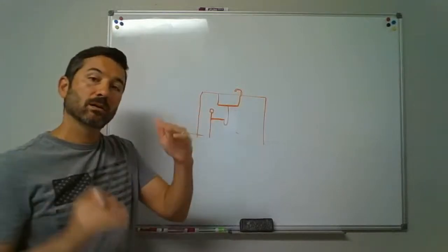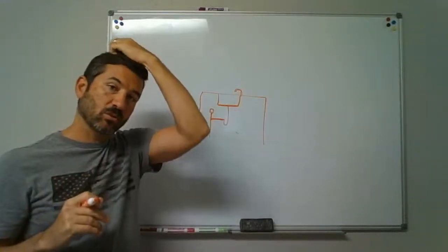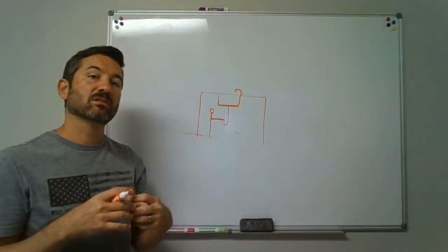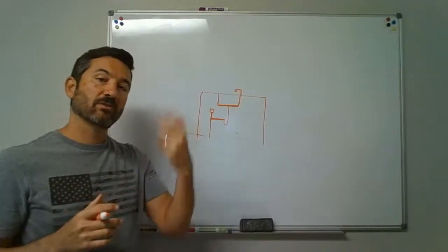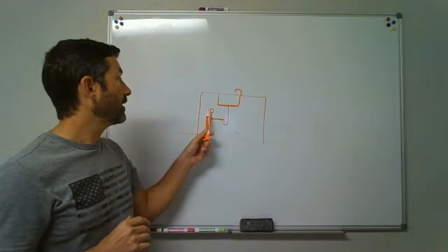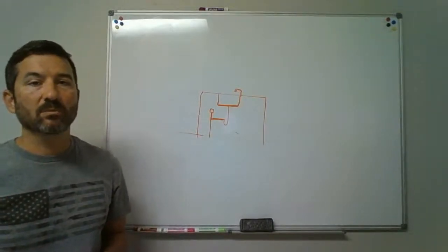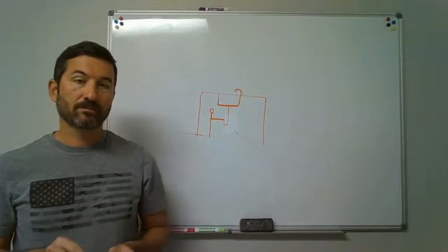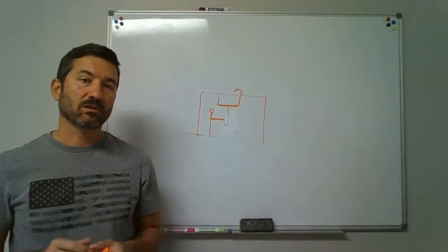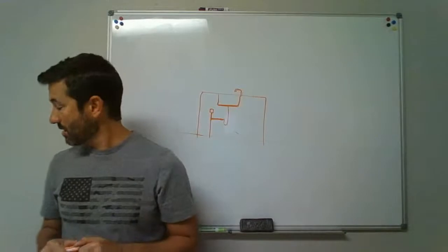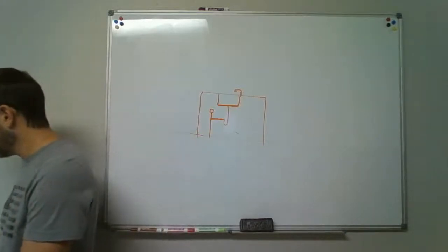It's a one-way check valve that's going to allow air to be drawn into the system, and it will seal off and keep the gas from coming out. And that's what you're really going to see most of now, because that's going to save you a lot of time and money on the extra routing that the other one's going to cause, and you can just slap an air admittance valve up on there.